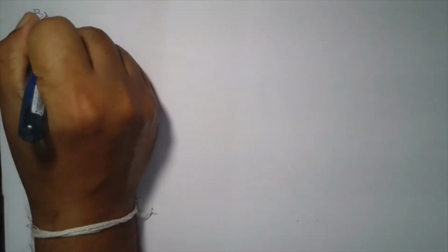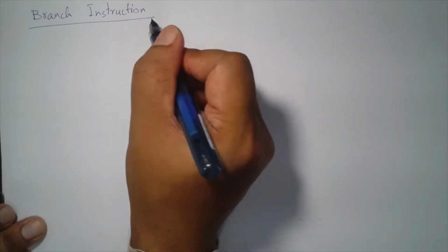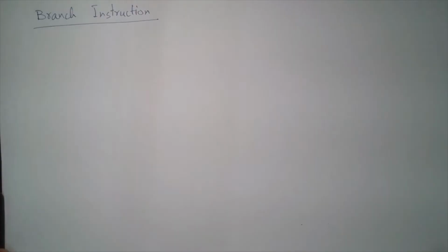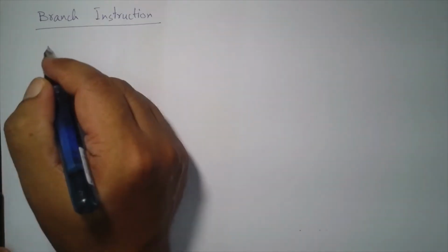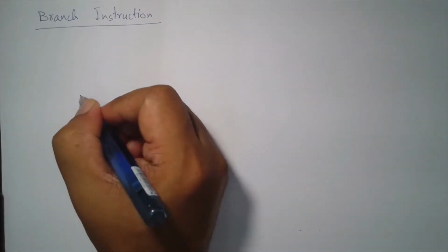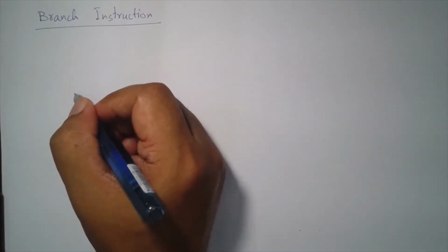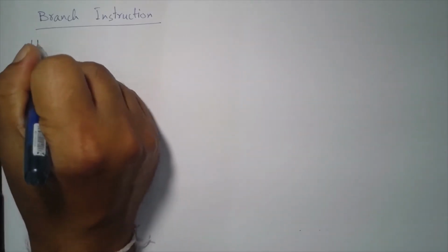Okay. So now another very important set of instructions is branch instructions. As the name suggests, a branch instruction changes the flow of your code. So generally you fetch instructions from the next location and so on, but a branch tells you that you are not supposed to fetch the instruction from the immediate next location in this specific sequence. You have to branch to a different location. So now branch can be of different types. The simplest of them is unconditional branch.